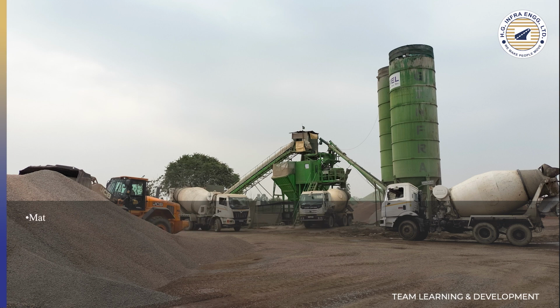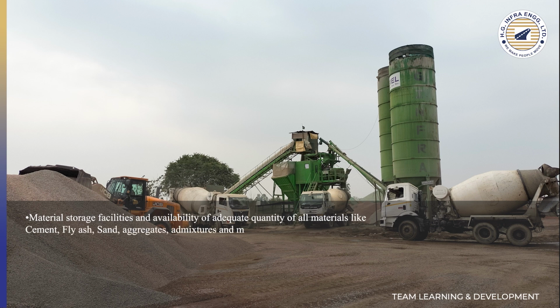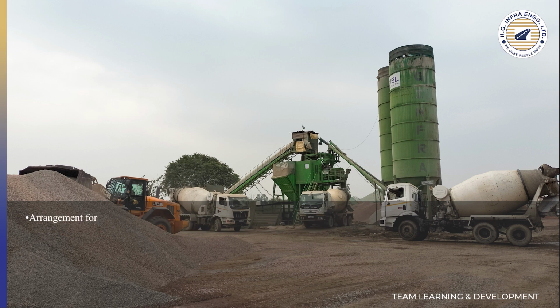Material storage facilities and availability of adequate quantity of all the materials like cement, fly ash, sand, aggregates, admixtures, and microsilica are maintained at the batching plant before commencement of concrete. Arrangement for workability control, batch record sheets, and slump.